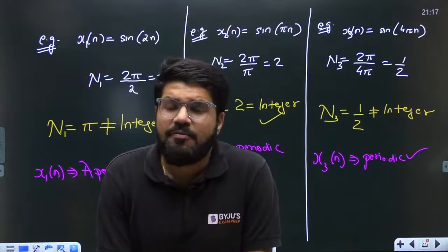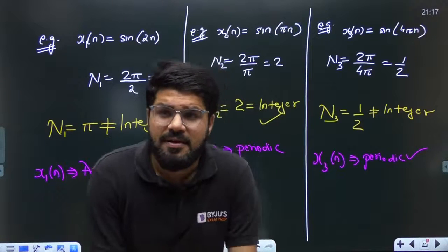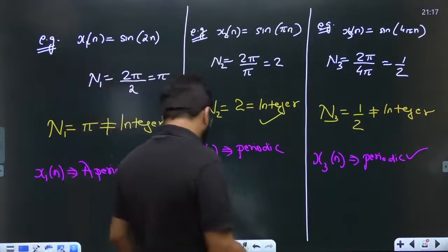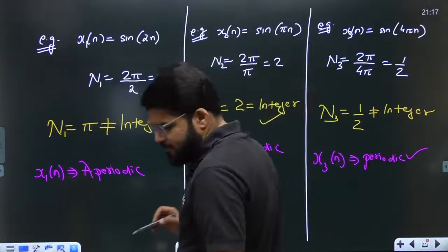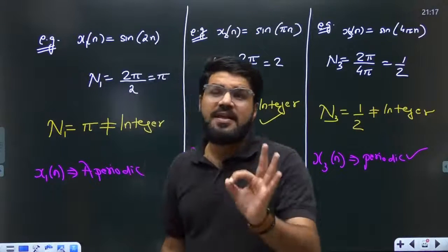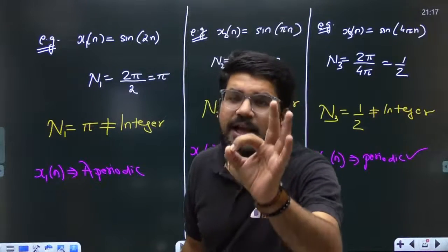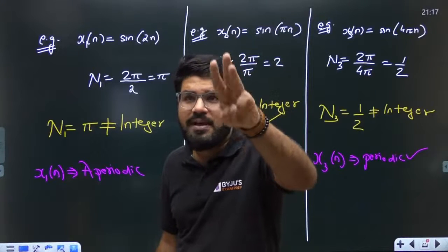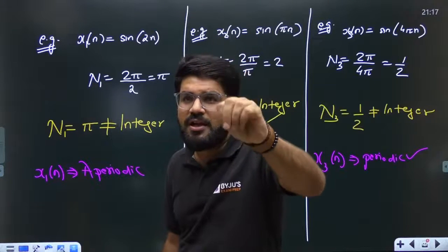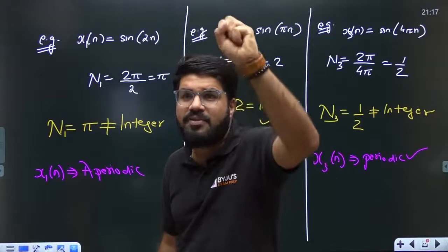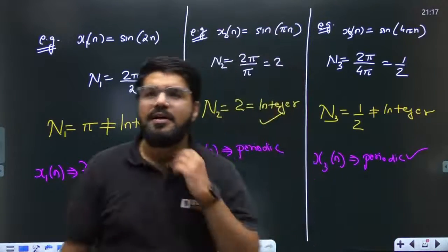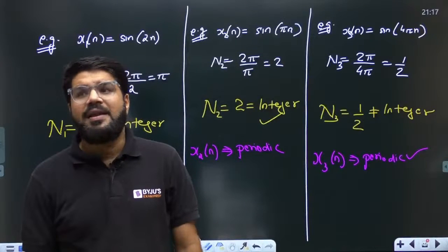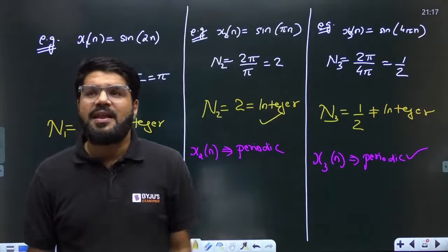We know that the period for a discrete time signal can only be an integer. Discrete time signal is defined only for integral values of time. So dear, understand the point here. I told you one thing: if a signal repeats after capital N, it will repeat after 2N, 3N, 4N, 5N, 100N, 200N, after every N. It will repeat after kN, I can say.